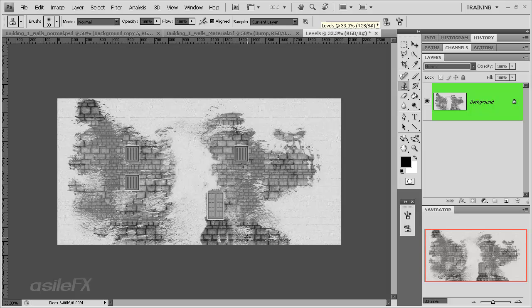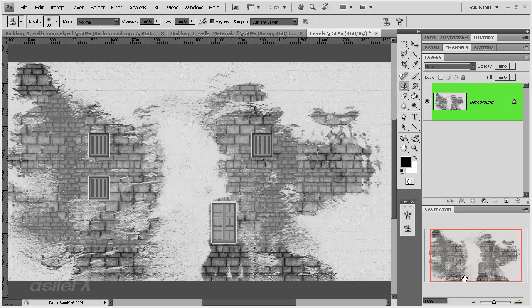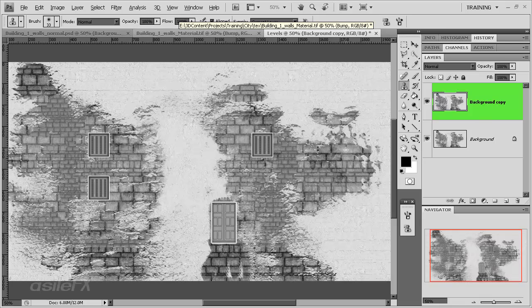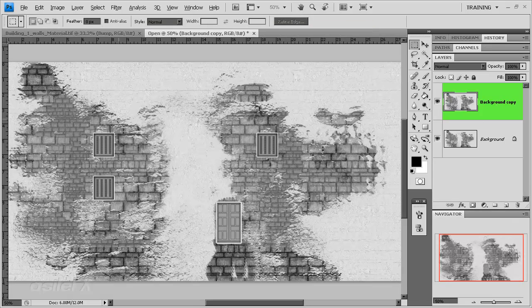So going back to that duplicate, we can run the NVIDIA normal map filter. I'm going to duplicate the layer, so we have two. I also need to close Photoshop and open up the 32-bit version because I am using 64-bit at the moment. There are a lot of ways to use the NVIDIA normal map filter, working with multiple layers.